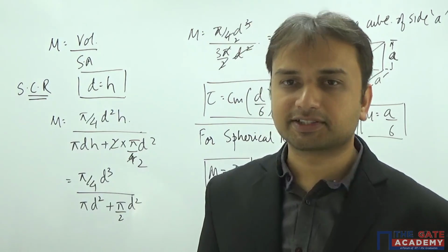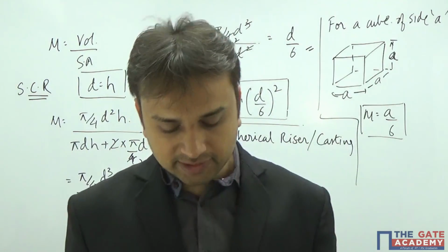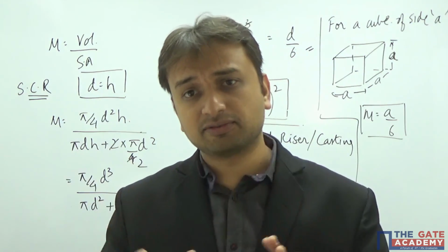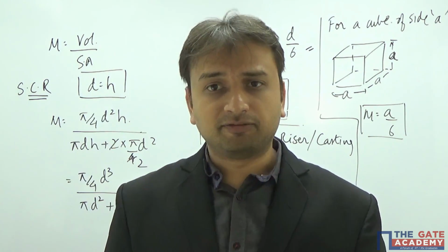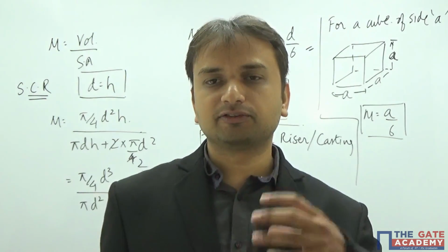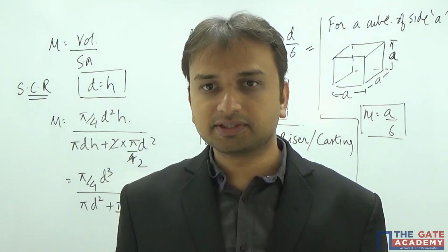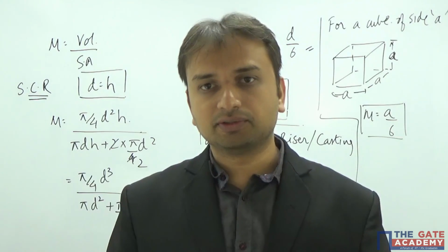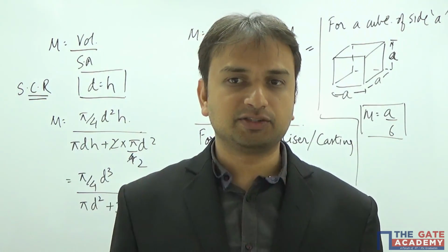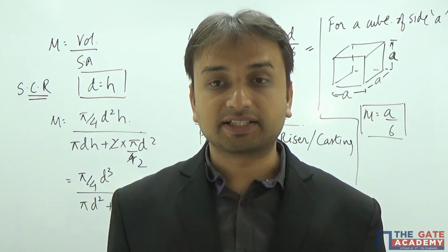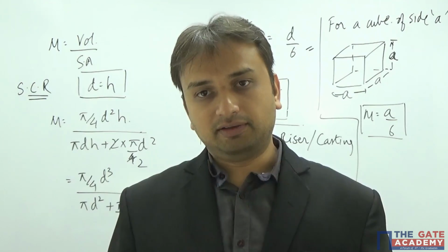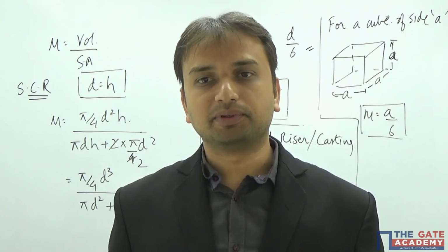We started our discussion with the shrinkage happening, and that led to a discussion of why the riser is used, and what is the difference between the functionalities of the riser and these allowances. That we have understood: allowances are used only for solid shrinkages, whereas riser design is used for liquid contractions only. Fine. After which we started discussing the riser design.